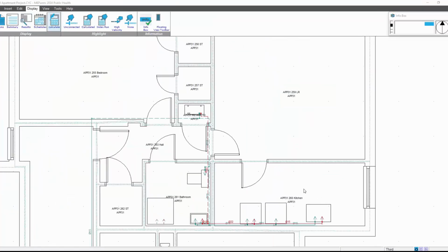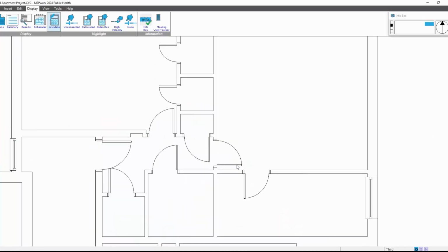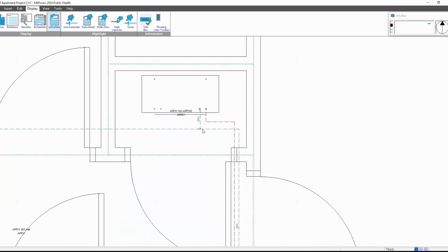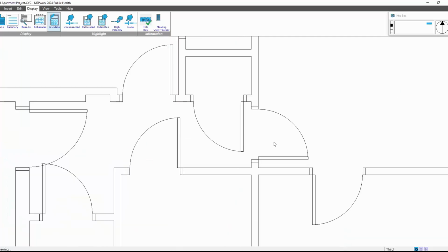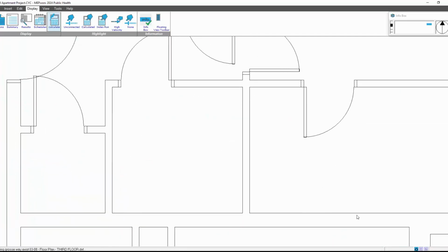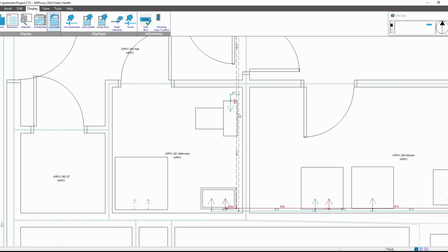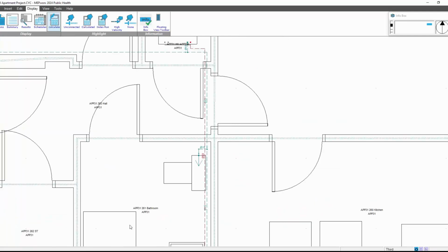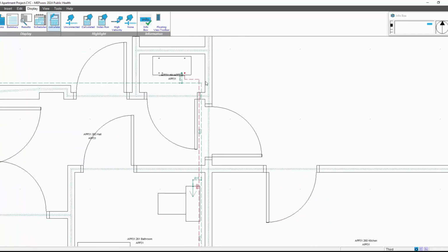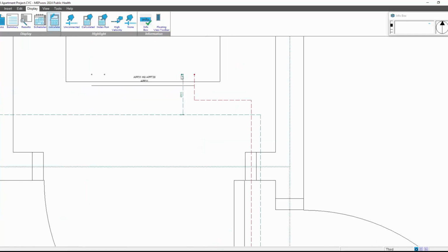Moving into public health, we can connect the secondaries and the hot and cold water to our heat interface unit. So effectively, you are tapping in your main system to your appliances. Here we have dishwasher, sinks, toilets, etc. Yet to pipe up the shower. And also we've got our hot water connection, which is served as an entry point. So the cold feed is effectively a load. So you start at the load end and connect into the pipe run. When you run the hot water circuit, that is effectively the entry point of the system.